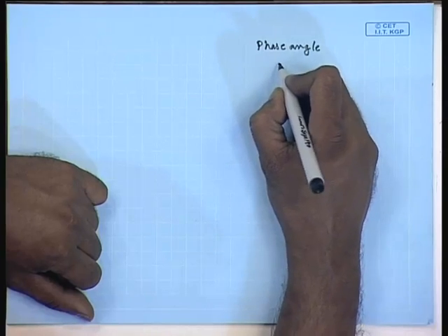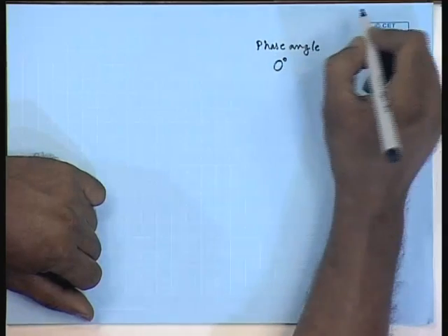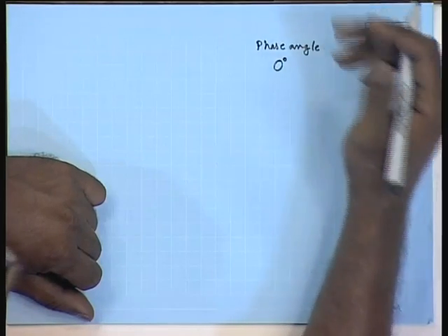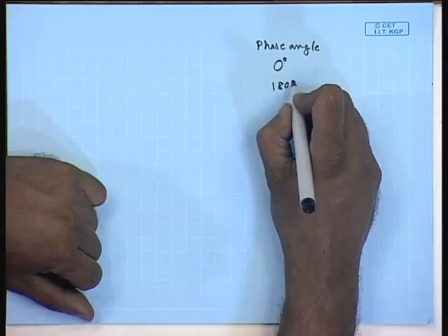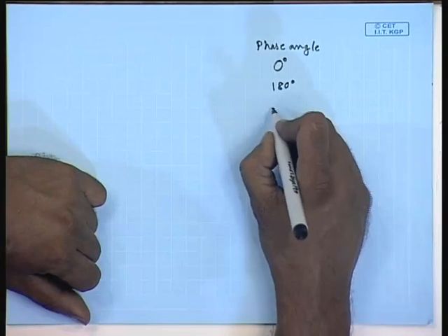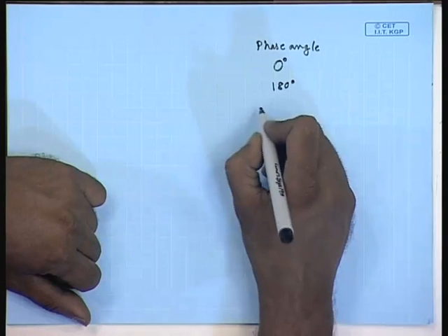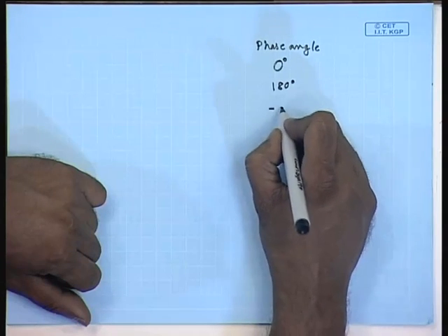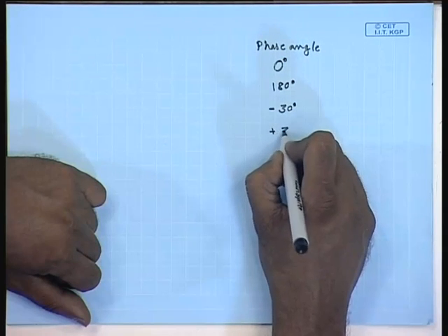The phase angles can be either 0 degree, that is the line to neutral voltage phasor of both sides may be co-phasor, or 180 degree, that is they may be opposite in phase. The low voltage winding voltage phasor may lag the high voltage winding by 30 degree, or it may lead by 30 degree.